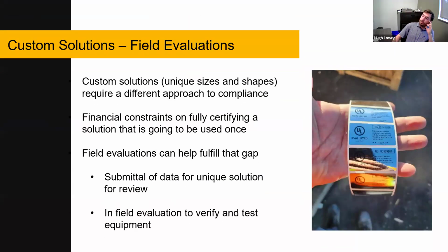One thing we didn't mention previously as well is the approach to certification. So we have the IEC 61730 that I mentioned previously. So that is a factory level certification. Typically, you would get that on one model and one size, and then you would go ahead and mass produce that particular model and that particular size. This became a bit of a challenge for us as we got into customized projects. It became a little economically unwieldy for us to pursue full factory certification on every single custom size panel that we were providing to our projects.